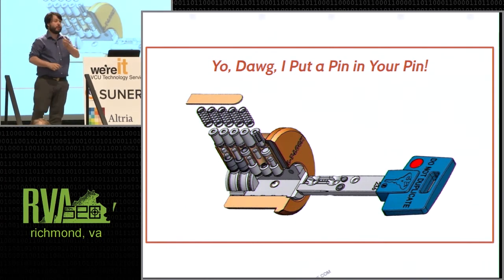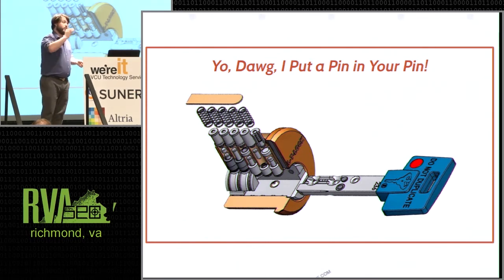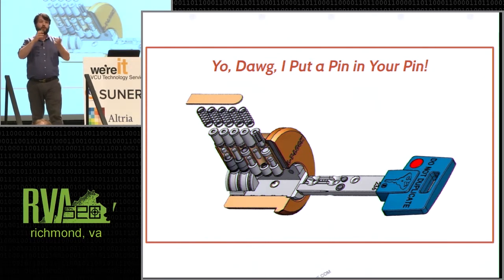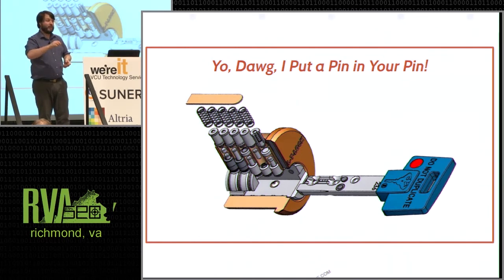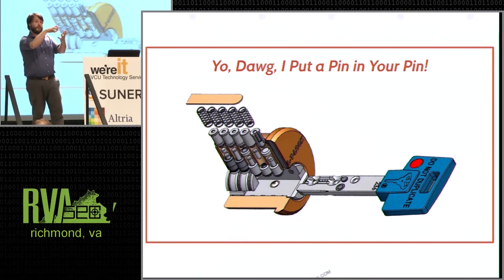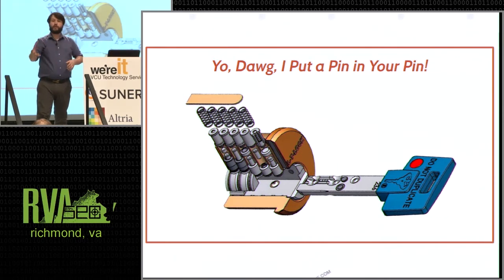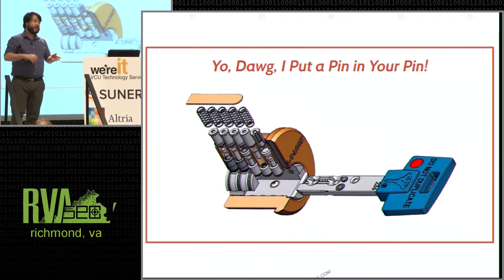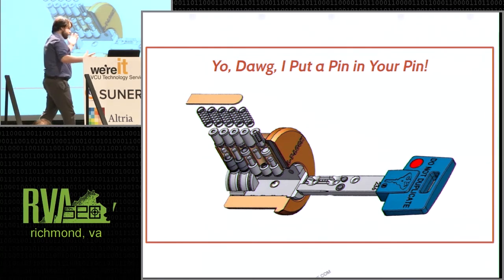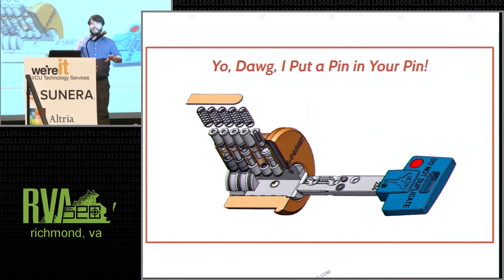That inner pin is so small, and the way that all of the rakes work is that it will lift both outer and inner pin to the same height. But the outer and the inner pins can actually be at different heights. They accomplish this in the key by milling in two circles, little concentric crater marks into the key. One will lift the interior pin, one will lift the exterior pin, lifting them both up to different heights, and it's super cool.